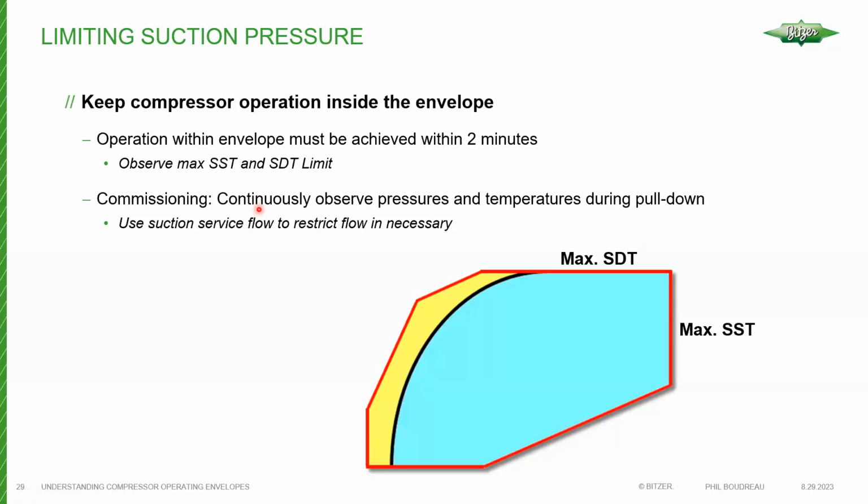So during startup, it's very important that we observe the pressures and temperatures during pull down. So we're looking at actual pressures and comparing them to the limits, and also the minimum allowable superheats entering and leaving the compressor.